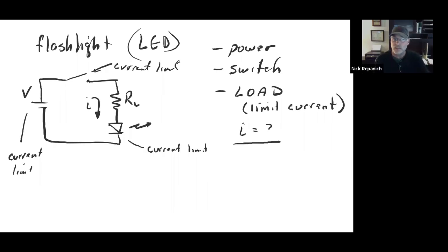You run 9 circuits, what happens? You're going to have an overloaded power supply, and it's either going to brown out, die, kick a breaker, or blow a fuse. And if you notice, I gave you some fuses, those little brown fuses. It's because you didn't do enough I equals on it, or you hooked it up backwards, one of the two.